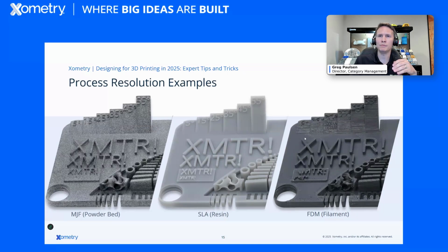And the more gradual that curvature is, the less steep the slope is, the more coarse it looks. And as it's going more vertical, you tend to get better results. This is probably a worst case scenario print, but I really used it to emphasize the differences between the different outputs. So depending on your part design, you may be going to one process versus the other.